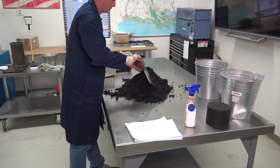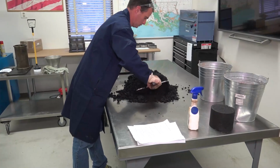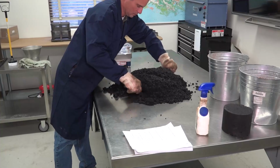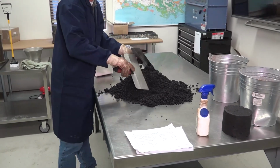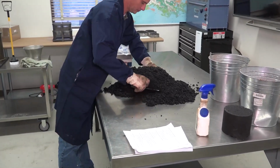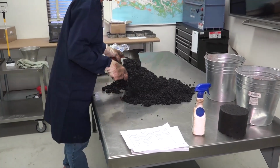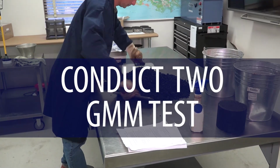The precision of the method is best when the procedure is performed on samples that contain aggregates that are completely coated. To ensure complete coating, it is desirable to perform the method on samples that are close to the optimum asphalt binder content. During the GMM procedure, we will conduct 2 GMM tests.